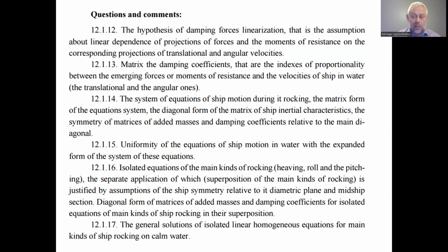These factors we used in the canonical equations are within the matrix, and within the matrix, these factors have two indexes. One index shows in what direction we determine the displacement. The second index shows on behalf of what effort we consider the displacement in the first index direction.